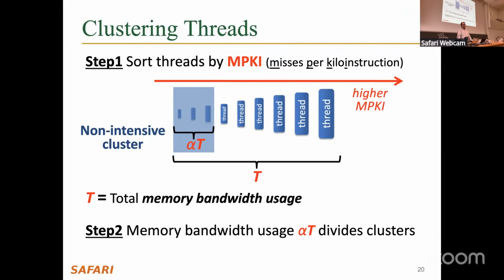But before executing the thread, the scheduler needs to schedule them. No. The scheduler that you're talking about is the OS scheduler. Oh, okay. We are in a different scheduler here. The OS scheduler does that in a much less fine-grained manner. Usually it's around milliseconds, or sometimes if you are very lucky, it can be in microseconds, but usually it's milliseconds. But here we are talking about nanoseconds. So there are some threads that are already scheduled by the OS, and now in the hardware, we need to schedule them. Good question.